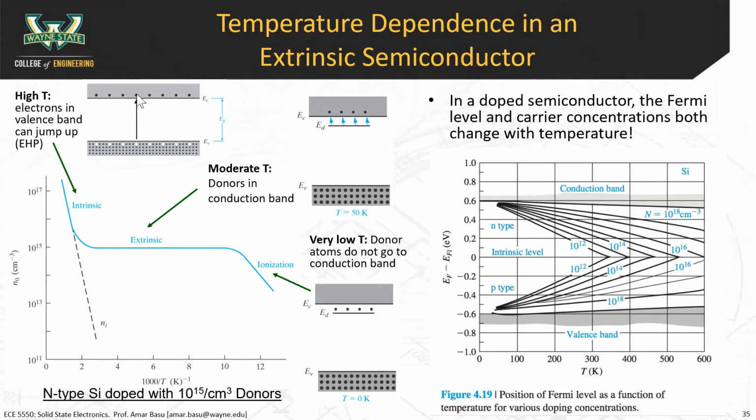So if I told you that the wafer was N-type, the answer would be the same. At high temperatures, it becomes intrinsic, with intrinsic-like properties. The use of the word intrinsic is a little bit confusing because intrinsic implies low carrier concentrations. But this is what they call it, because if you took an intrinsic material, an undoped material, and you put it at super high temperatures, then the same effect would happen. Does that answer your question?